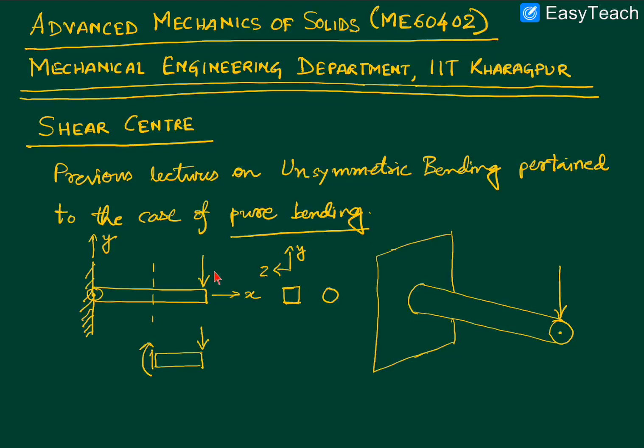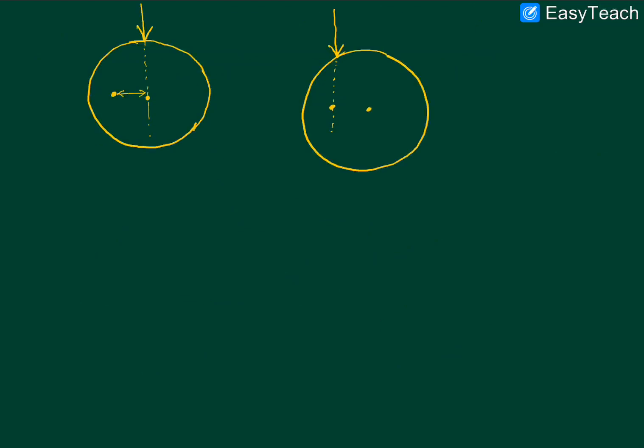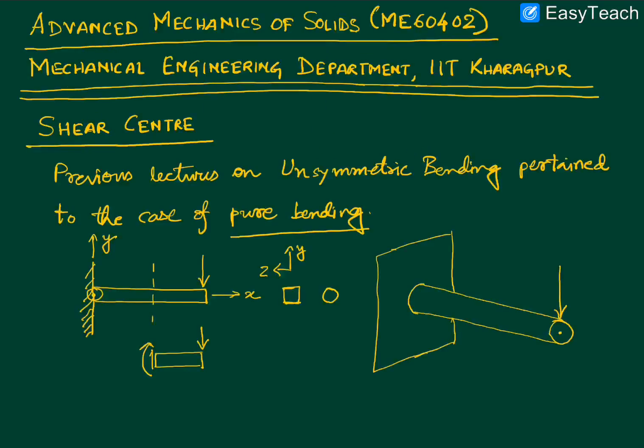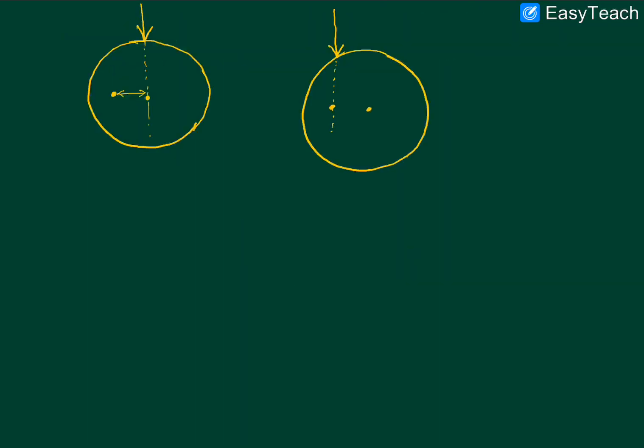But at the same time, if we look at the YZ plane, which we did here, and we considered this kind of a force which would still look very much vertically downward in the XY plane, but which is clearly off center looking at the YZ plane, we understand that the very same force which was inducing the bending in the previous page here would be inducing, along with the bending moment, some kind of torsion also.